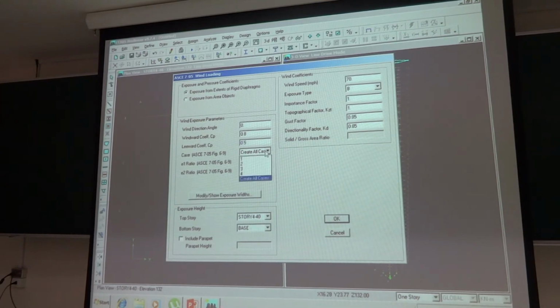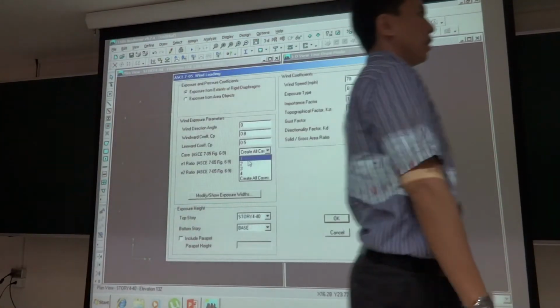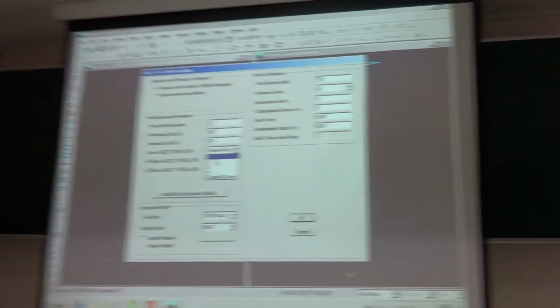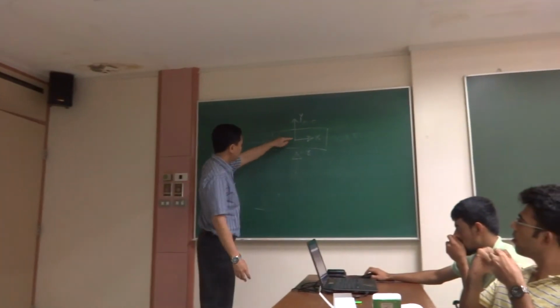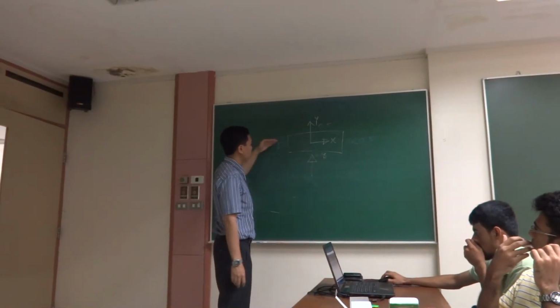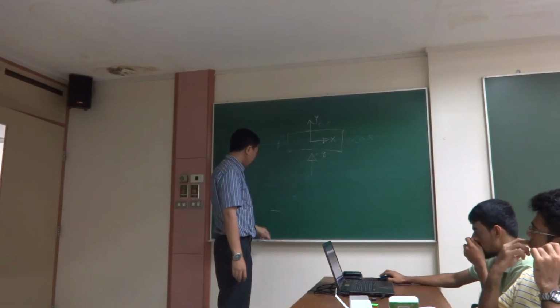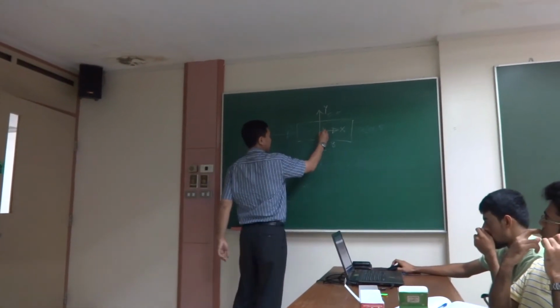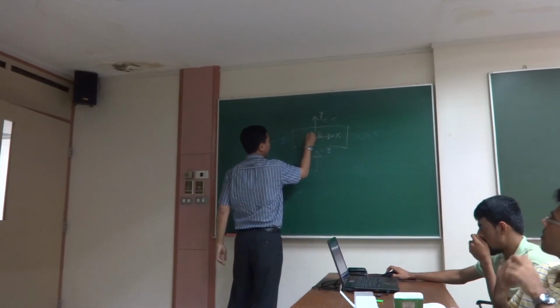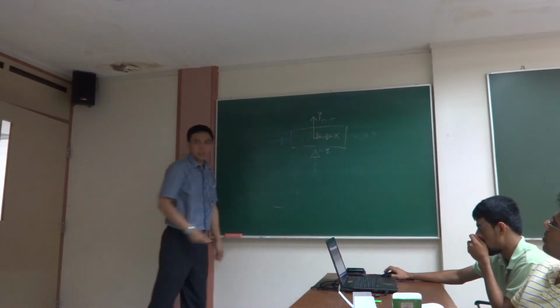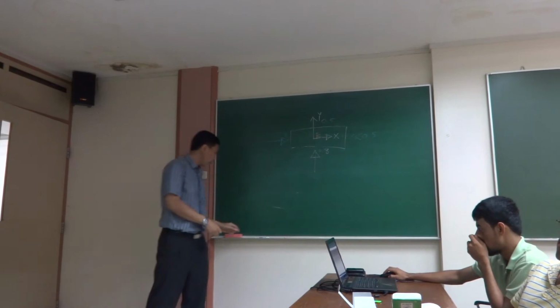Another thing is the application of the wind load. There are 4 cases in ASCE 7. Considering we are applying the wind load in the X direction, 100% of the wind is applied just at the center of the building, and also we consider some eccentricity. We apply the wind load here. So these conditions will be considered if you consider all the cases.